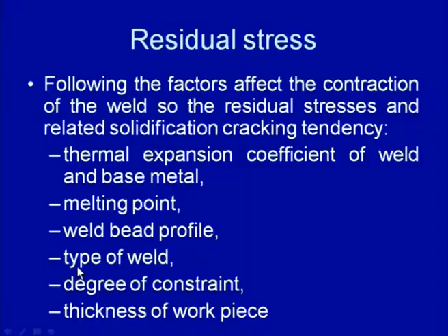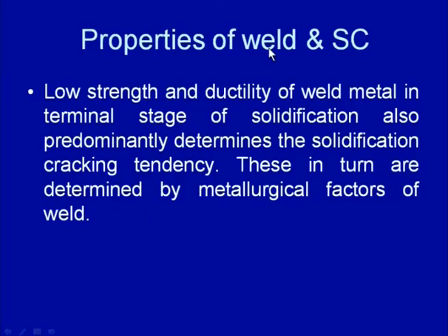For example, a convex bead promotes the solidification cracking tendency, while in the case of a fillet weld, a concave bead promotes it, while a convex bead reduces this kind of cracking tendency. Then there are the type of weld, the degree of constraint and the thickness of the workpiece. Increased degree of constraint and increased thickness will promote the residual stresses, and so the cracking tendency of the weld.